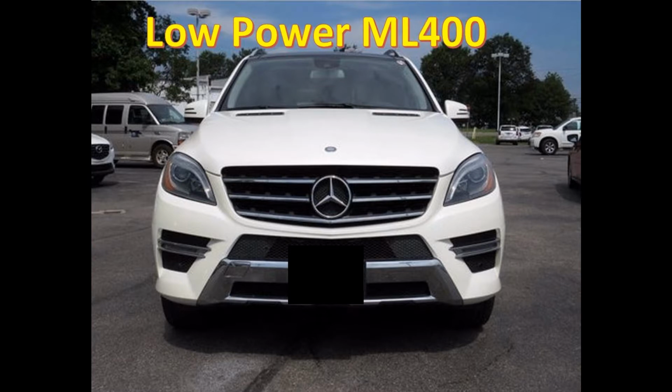Having said that, the car does seem to pull okay, which would indicate to me that we're not dealing with plugged exhaust or any of that kind of stuff. So it is down on power, but it's not what I would consider to be massively down on power to the point where it won't rev out. It will rev out. It'll go to 5,000, 5,500 RPM, that kind of stuff. And it pulls, but it doesn't pull as strongly as it should, in my opinion.